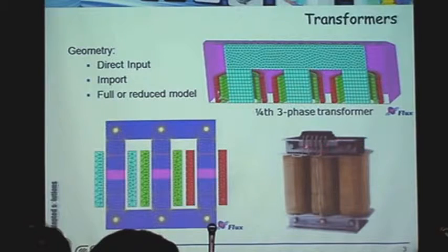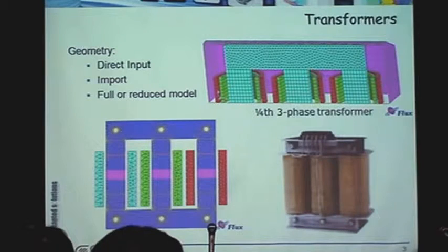Obviously, if we do something like this, you can see all the clamps on the side. You may have flitch plates and stuff like this. You cannot show those in 2D, and we're going to look at losses inside there. In 2D that would not appear because we would cut it right in the middle and we would not have those very important features. So it's going to be 3D, but then think about the number of elements you're going to have.